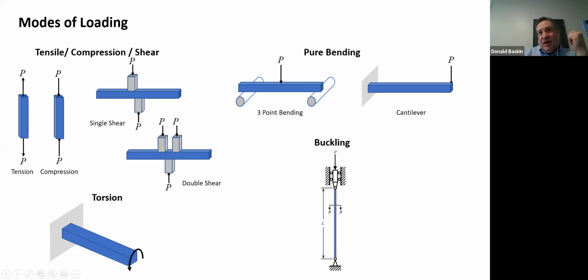If you look at the control arms, or the suspension arms in your car, and see how they're mounted to the chassis, in some cases some manufacturers screw this up. Chrysler messed this up a lot of times. They never had any failures, but there are certain cradle structures where they use single shear, which I always would object to.